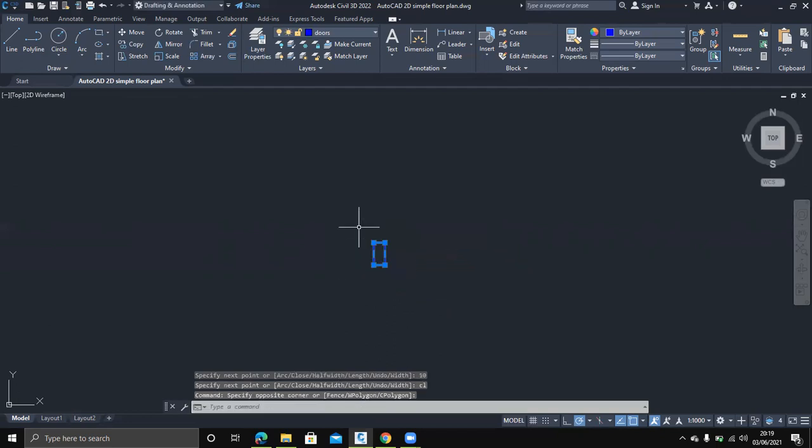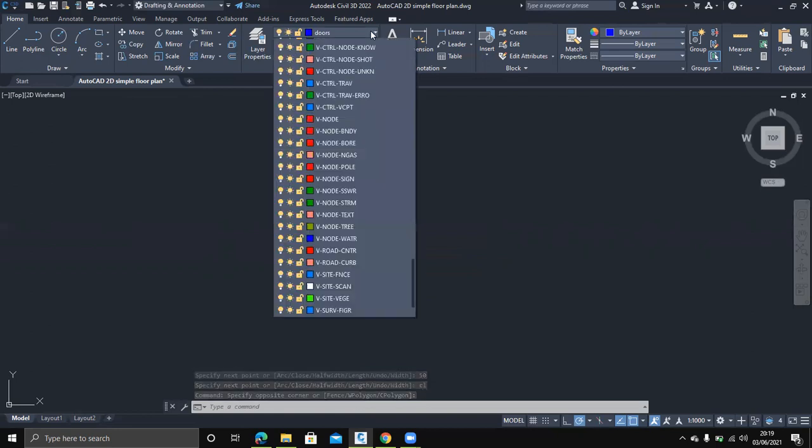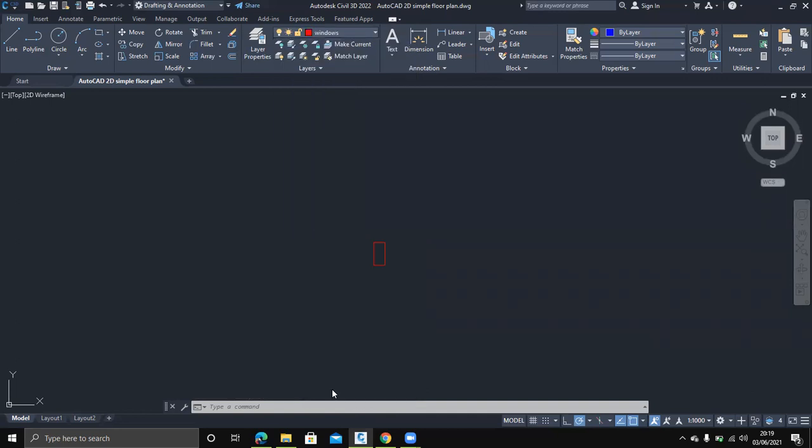Let me quickly move this one to the layer on our window, so that we don't mess our work. So you can see it has successfully moved to that layer, and I will also make Windows my current layer by just clicking that, so that I can draw on the Windows layer. So I will draw a line, some extension of 4 units from here. A line that is actually, sorry, it's not 4 units, it is actually 40. So 40 units from there.